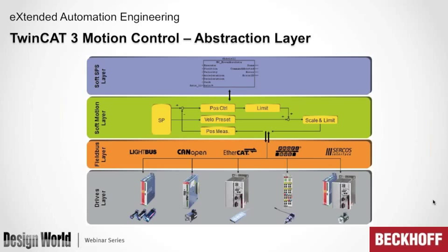So the concept of abstraction, we talked about it a little bit. This slide brings it home for me. At the bottom level are things I can drop on my toe, a drive, an I/O sensor, things I can drop. I put those together. I often have to do some configuration of them, and then I can now communicate, and that's the second level, the orange level. I now have a field bus that communicates that information from the device to a controller.